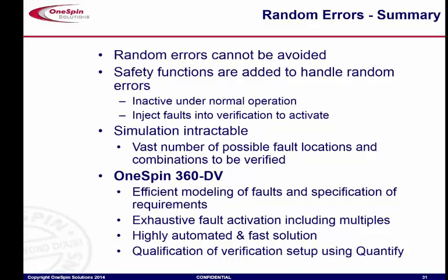And therefore, formal verification really lends itself very nicely as a new player here in the safety market, because you really just model classes of faults and candidate bits where faults should be injected, and then you can perform exhaustive verification for these specific mechanisms.